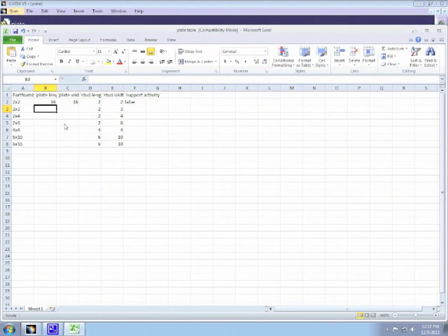One of the nicer things about design tables is you can actually use formulas in Excel rather than trying to use the formulas in CATIA. We can take advantage of this with this particular design table because the plate length and stud length are related by just multiplying it by 8 millimeters. So I'm just going to grab this, multiply it by 8, and fill this out.